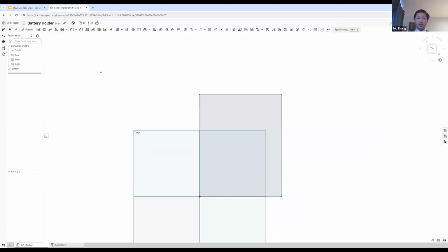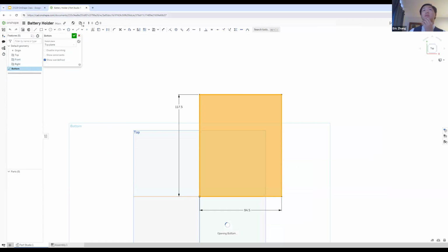All right. If you want to offset something, you could just press O, I think. That's not how it works. Well, I'll find it one of these days. Loft, extrude. Sketch tool. Oh no, it is okay. My bad. Offset is a sketch tool, so you need to double click on the sketch again, and then you can finally offset it.